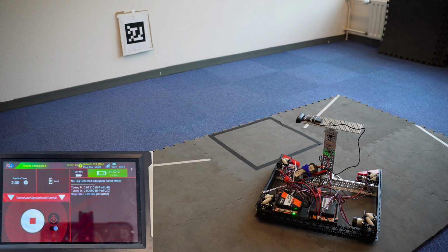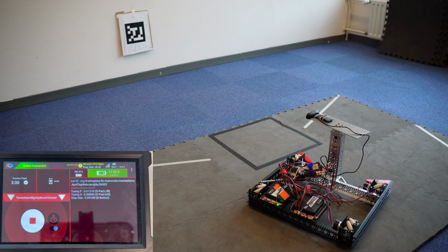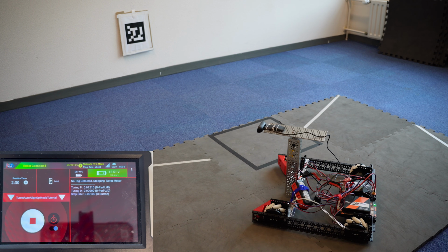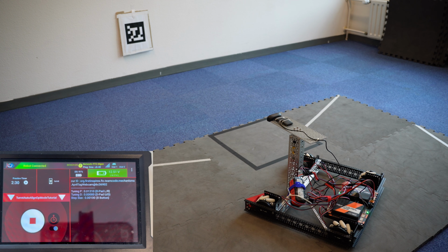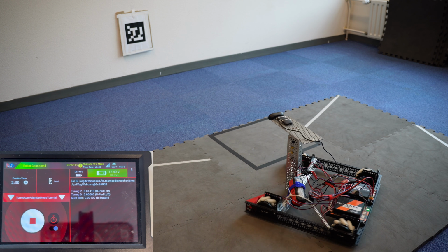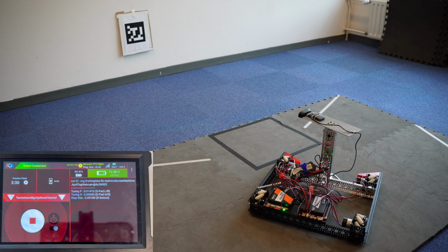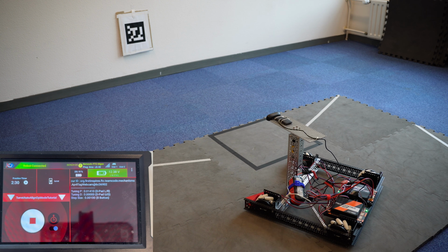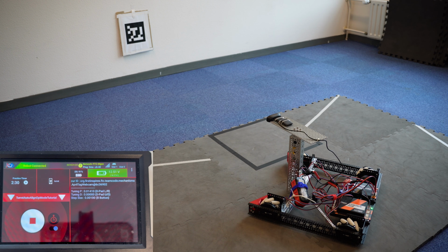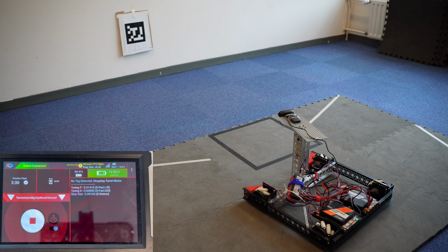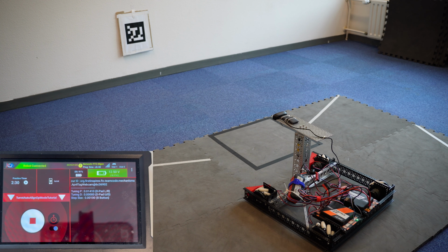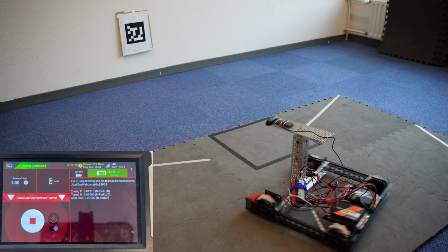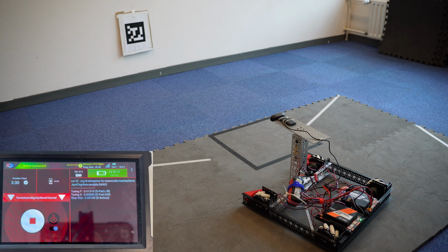That might be too low now, because as we rotate, it's not quite getting at the right speed that I would like. So maybe let's try 0.14. We get to the point where we get a nice little bit of moving, but not so much. And that's actually pretty solid. We're getting a little bit of overcorrection there. As I turn quick, you can see we get a little bit of overcorrection. It's probably still too much overcorrection, actually. So maybe I'll try 0.13. We can see that it actually wants to bounce forward and then back.